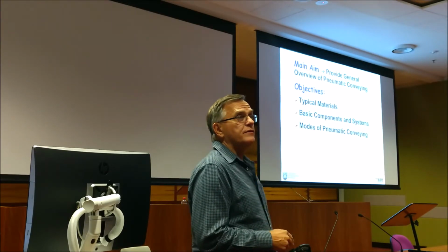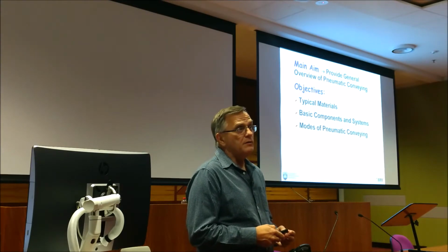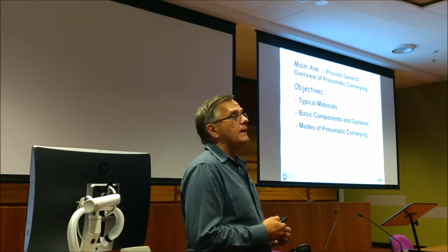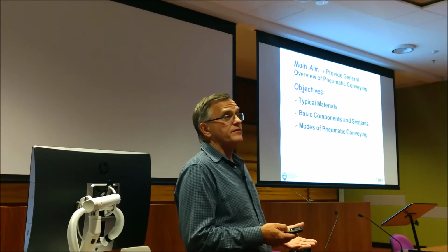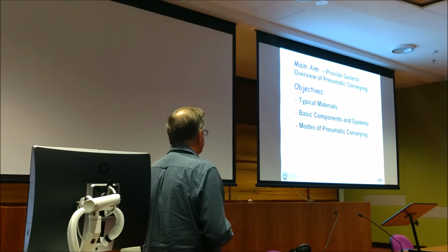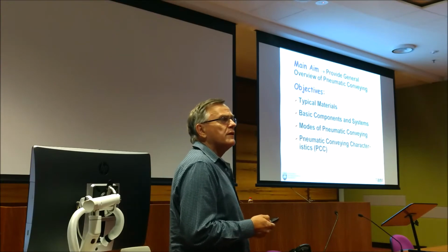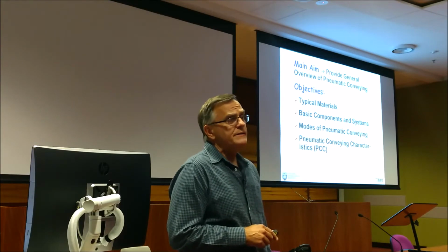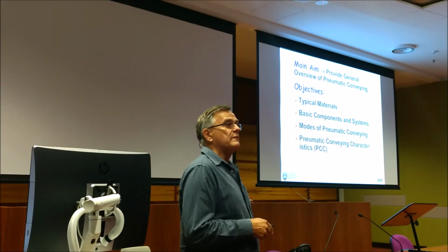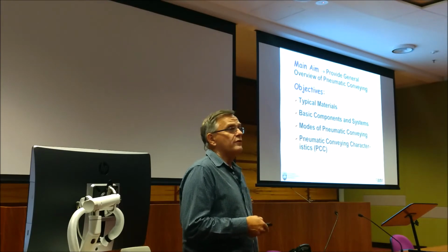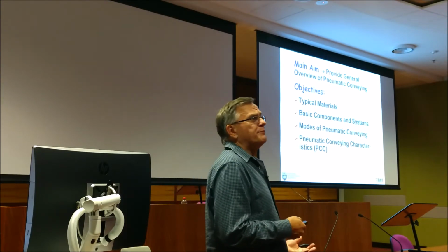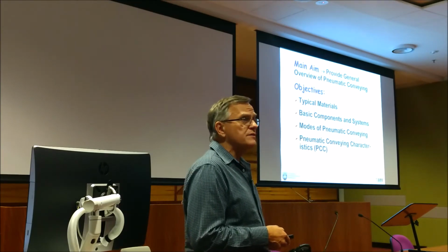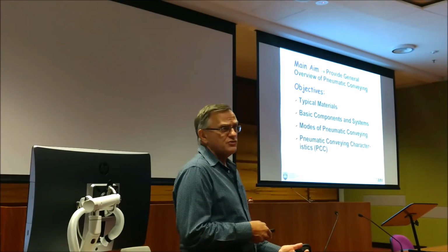And also introduce you to the different ways we can convey powders and bulk materials using air or gas. We call this the different modes of pneumatic conveying, and this is done for specific reasons, which I'll elaborate a bit later on. And for design and troubleshooting, we'd like to develop what we call pneumatic conveying characteristics. These are essentially performance curves. If you work with fans or pumps, you've heard of fan curves and pump curves. Well, these are product curves. For a given pipeline and a product, we like to generate some performance curves, which we then can use to design or troubleshoot the system.